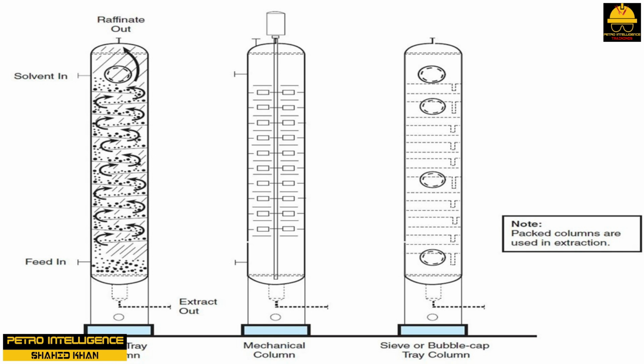A baffle tray is a device for breaking up the countercurrent flows to provide mixing. Baffle trays could take the form of disc and donut trays or crossflow trays. Obviously, contacting is less efficient with such an arrangement, but it is simpler and less susceptible to plugging than our sieve and bubble cap trays.